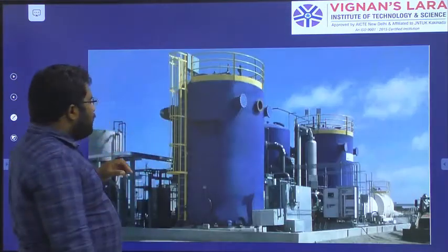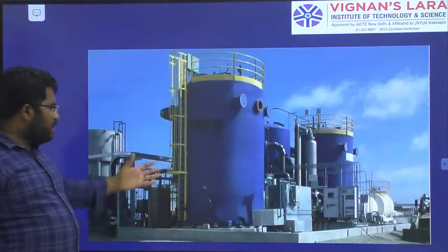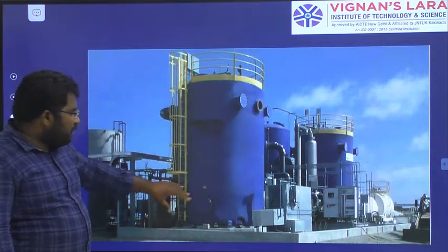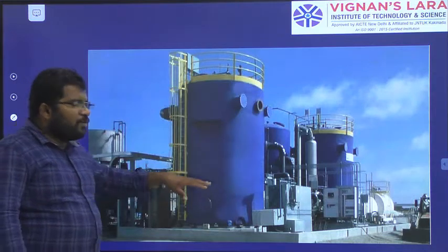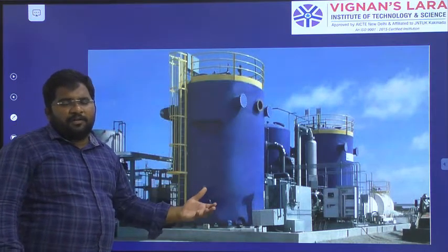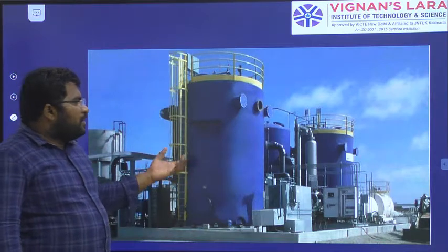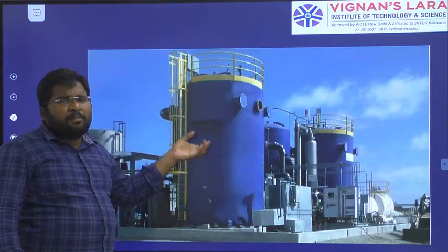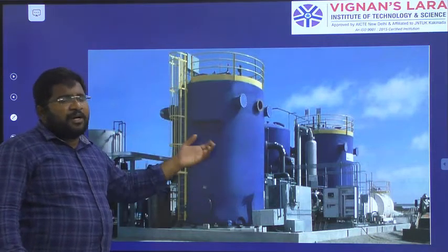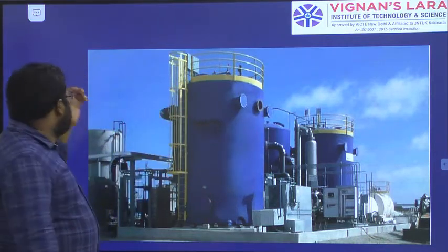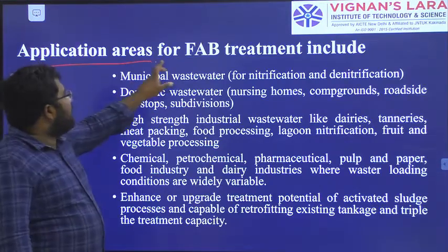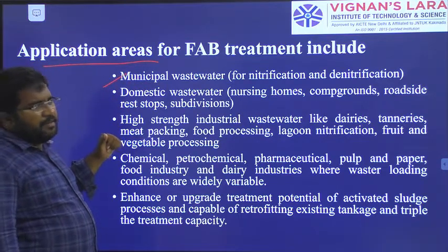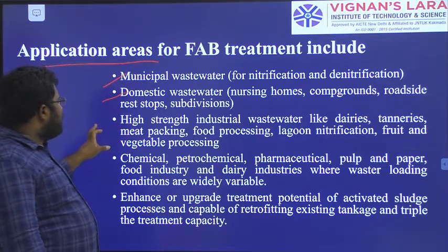Okay. This is actually, you can see, the treatment in actual days, right? So this is the thing where we have one side. We will send air, with the help of oxygen or any diffused air, so that the water and the media mix thoroughly, so that we have maximum BOD removal efficiency, right? So application areas for FAB treatment include municipal wastewater for nitrification, denitrification, domestic wastewater, and